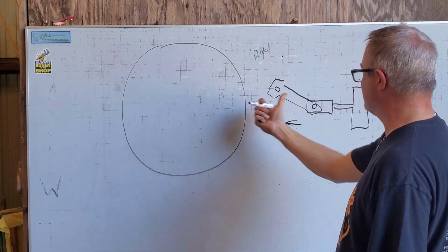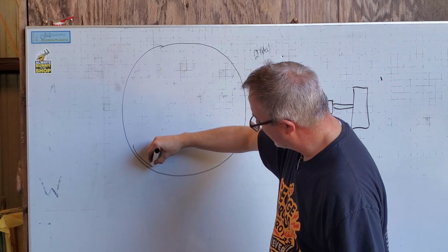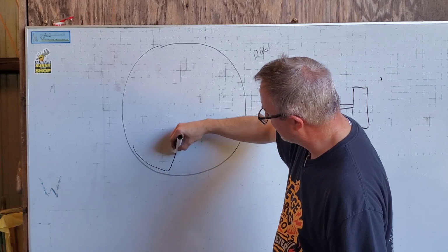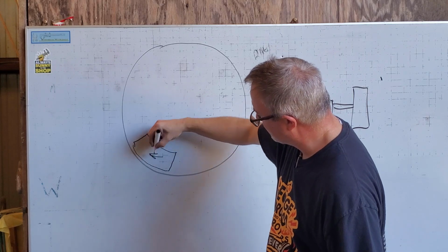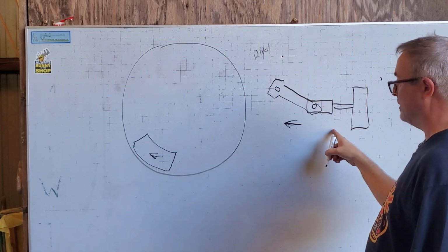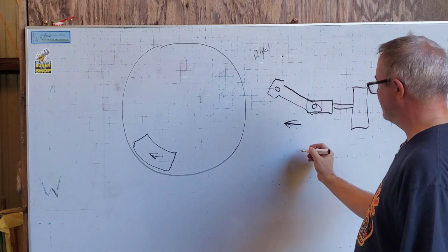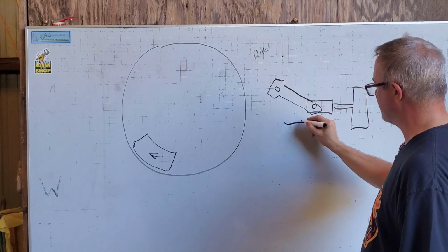Now, as this approaches front dead center, you can put a big counterweight on the crank out here, so that the velocity and the mass of this counterweight, the horizontal component, matches and opposes what's happening with the piston. Actually, this one will be going this way.